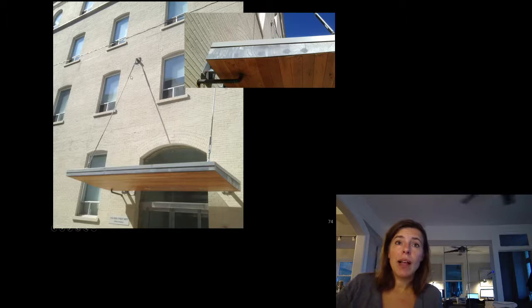Here is that classic system where we have the tension cables. You can see that they have big plates connecting into the existing brick masonry, and these are cables with elements that allow them to tension it. So these couplers allow them to actually tension that cable, so they've probably actually gotten it to work so that they'd be unloading the cables in wind load.